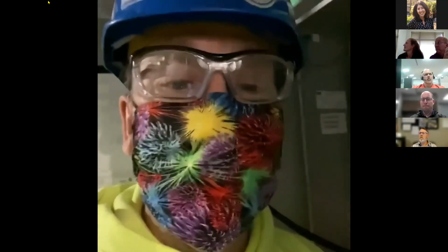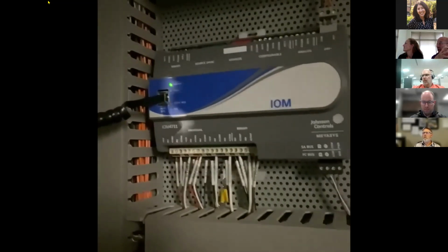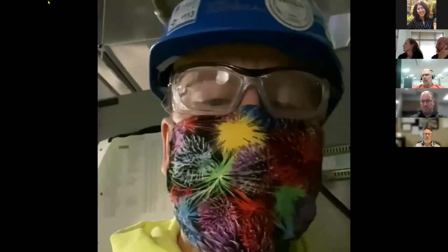So I'm back. I made a mistake. As you see here, there are multiple safety resets. There's this master reset, but then there's also the resets on the static pressure safeties themselves. Sorry, I'm doing the camera backwards. I'm not an expert at this. So the resets have now subsequently both been pushed. The high safety, which was this guy, and that guy, which then made the unit start.